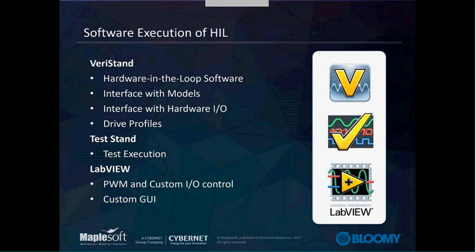And it allows us to apply drive profiles. What happens to your model as you run through a charge or a discharge or some other type of performance profile. We use TestStand to create test execution capabilities to run through tests in a repeatable and consistent fashion, and use LabVIEW for custom signals such as PWM and custom I/O, as well as custom GUIs if you need an interface that specifically meets your test need.